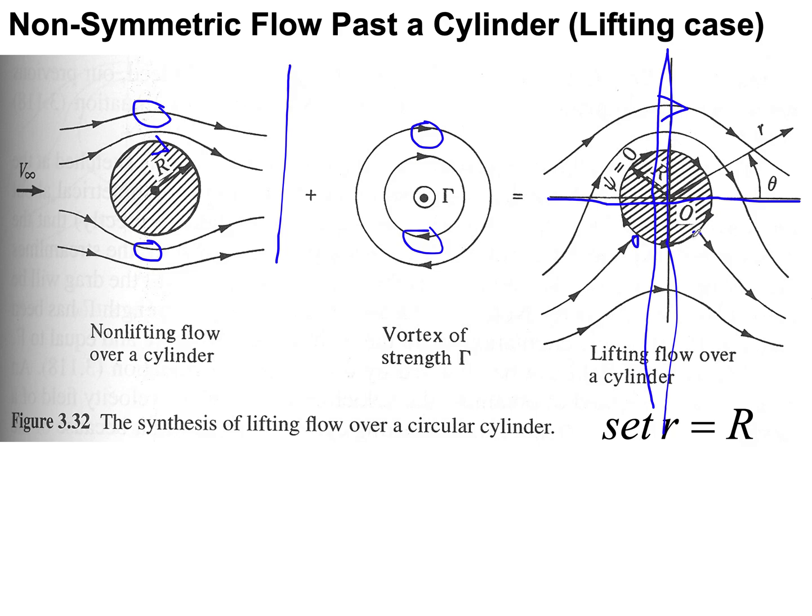You see you have stagnation points here than it is on the top, which means I expect higher pressure at the bottom than at the top, and lower pressure at the top, which means that is going to generate lift for me. So you see, with those four or five elementary solutions that we have started looking at, we were able to do closed form shapes like the Rankine object and the semi-infinite Rankine, and then we moved on to do a circular cylinder, but all of them were symmetric,